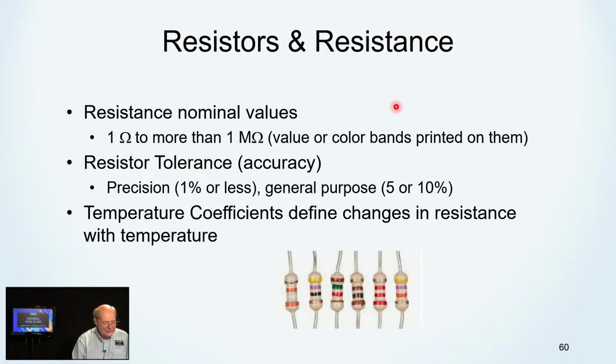So there's nominal values. You might have a resistor that's supposed to be 1 megohm, for example, but there's typically a tolerance: 20%, 10%, 1%, meaning that when you buy that part, it's guaranteed to be within this tolerance. So it'd be 1 megohm plus or minus 1% if that's what you paid for. The higher precision resistors cost a little bit more.